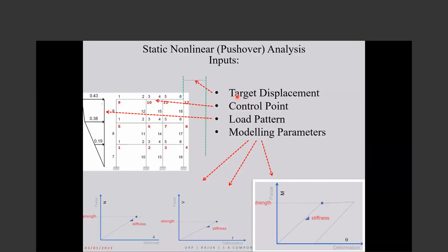So look at the elements: wherever is damaged is a good estimation of the real damage. Look at the forces: is a good estimation of the forces. Deformations: when you push a building nonlinearly to target displacement, then you can evaluate your acceptance criteria for whatever engineering demand parameter is considered by your code. If a code asks to check the drifts, we'll check the drifts.